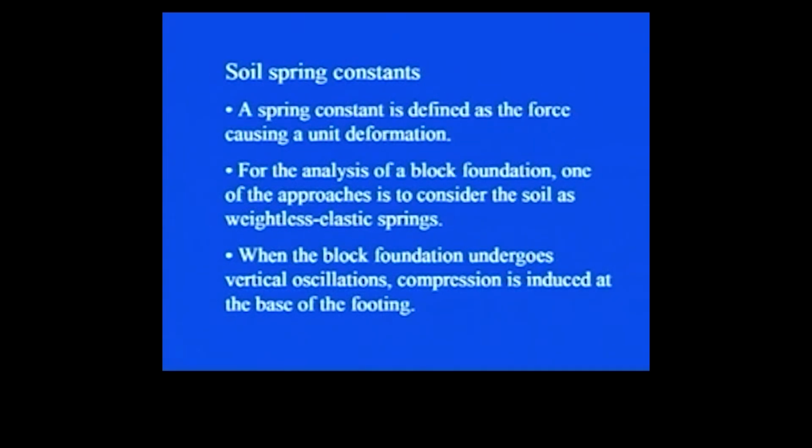A spring constant is defined as the force causing a unit deformation. So wherever I use the spring constant, this picture should come to your mind: the force which will cause unit deformation. For the analysis of a block foundation, one of the approaches is to consider the soil as weightless elastic springs. Since we are talking of the analysis of a block foundation, the soil is modeled as a series of weightless elastic springs.